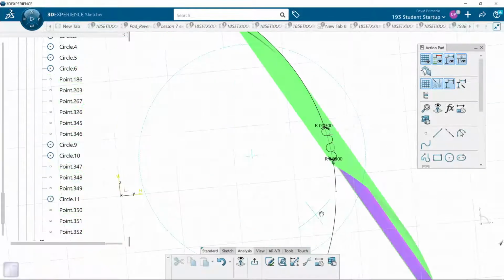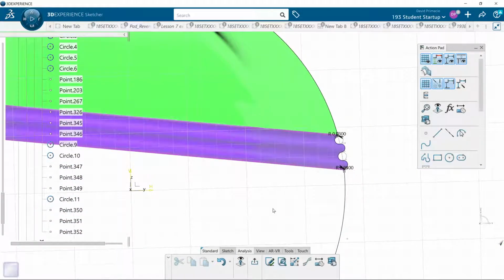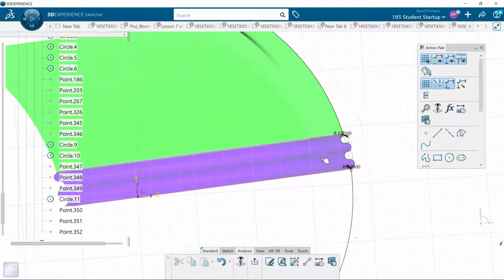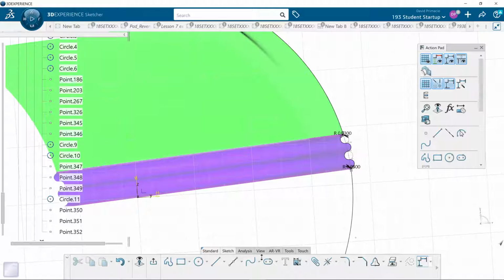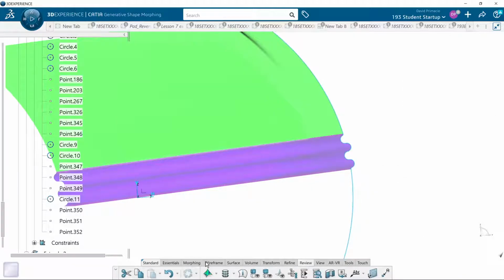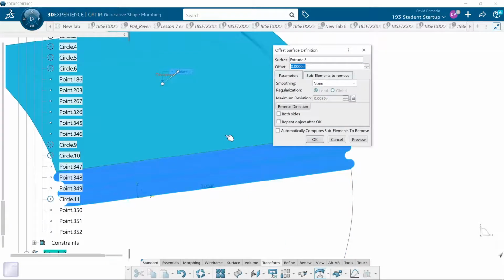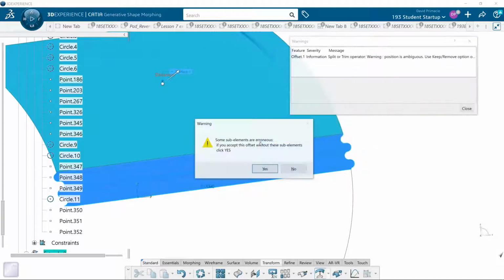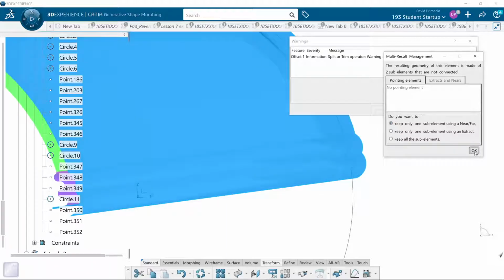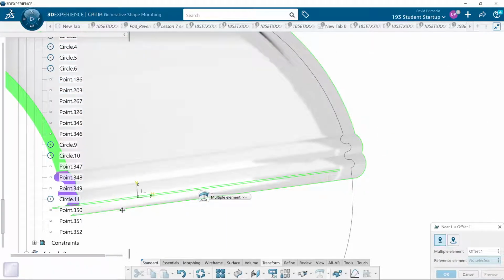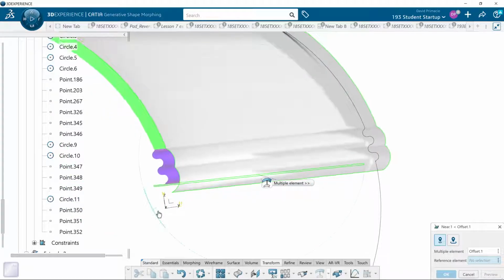Plus, let's say that radius is 0.3, right? And I need to do a Teflon finish a 1/4 inch apart. What's going to happen when I try and offset this a 1/4 inch? So if I grab this surface and grab this, and I try and offset it a 1/4 inch, why do I get an error message? Because you shrunk that radius.